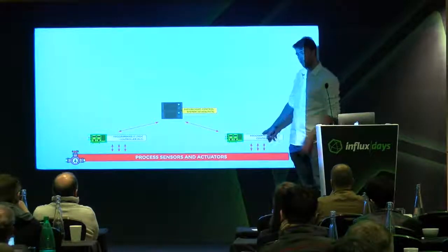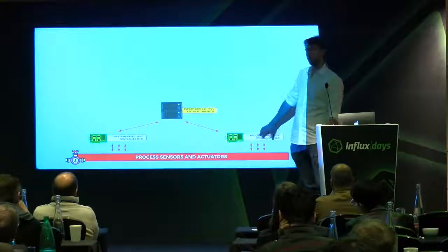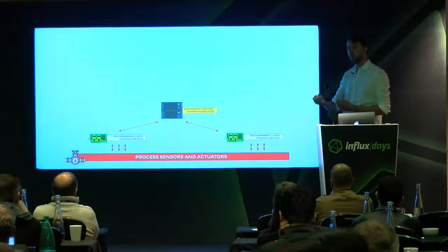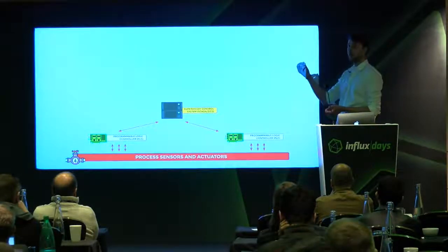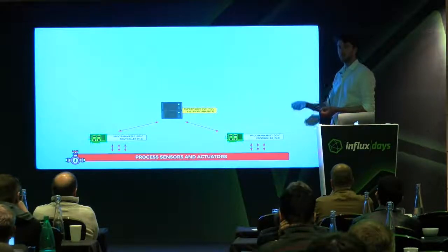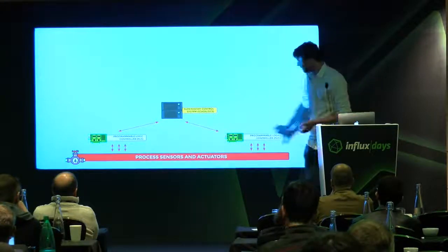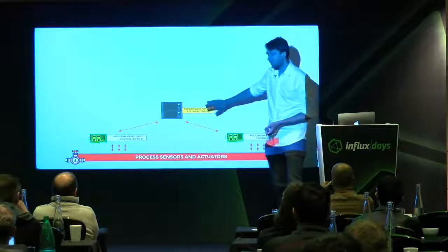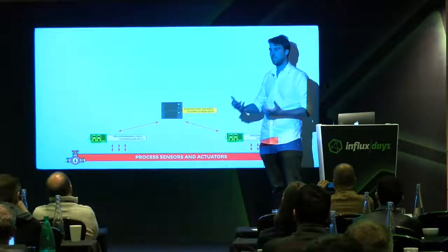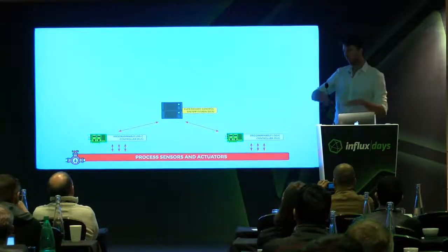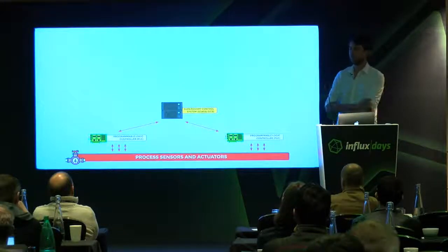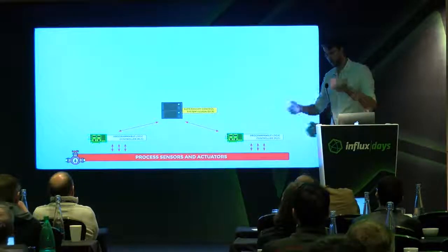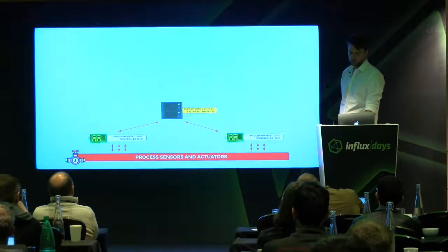These sensors send their input to a PLC, a programmable logic controller, which then does something with it and gives a signal back to an actuator to control the process. For example, if the temperature is too high, I will slow down any heating, or I will start cooling. All of this is managed by controllers, and if you have a lot of these processes, typically there is also a supervisory control system, which we call a SCADA system. SCADA systems control many sub-processes, are connected to many PLCs, and thus control a whole process. And a lot of human interfaces are also connected to that.